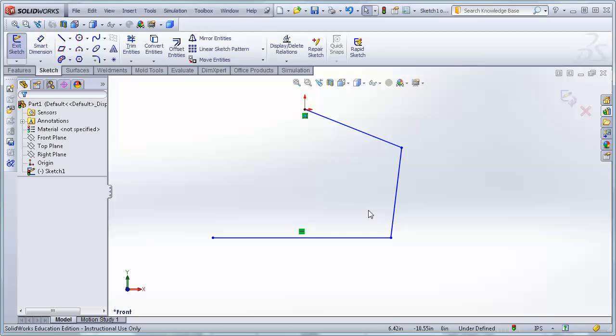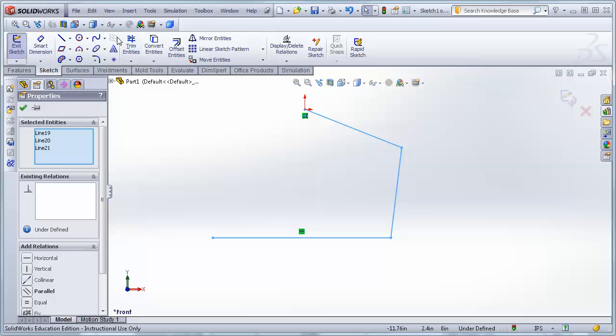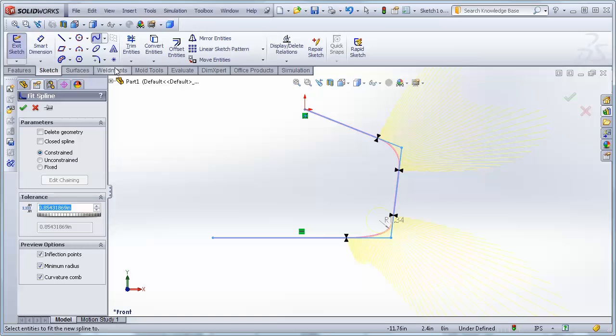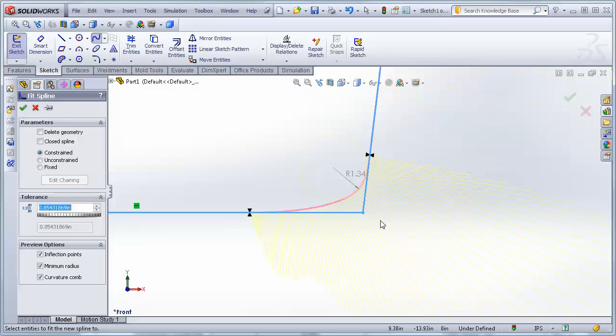Okay, I paused for a moment to make sure I understood the fit spline a little bit better, and I knew this, I just forgot. Basically, a fit spline says, let's start with a geometry that exists, and then one command, fit a spline to that geometry. And what it did, because this is an open figure, is it fit not a perfect fillet or an arc of a circle, but it fit this pink spline to this angle.